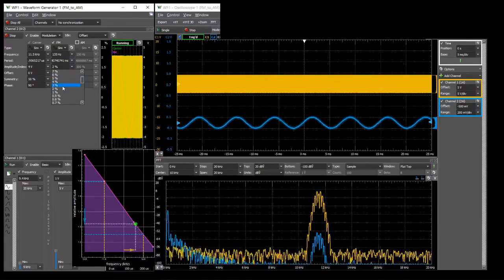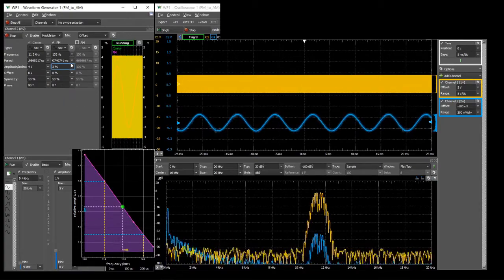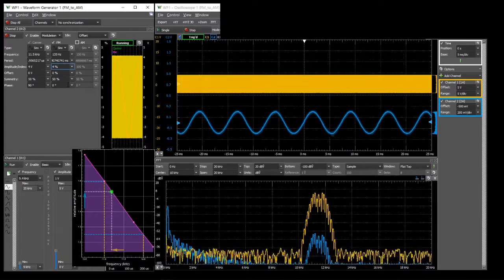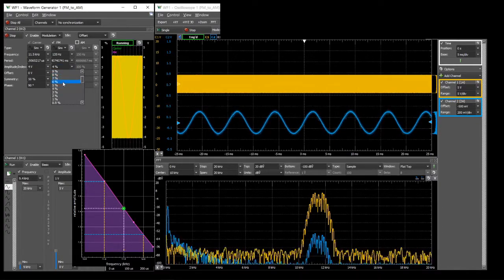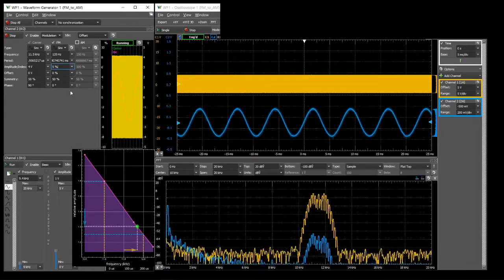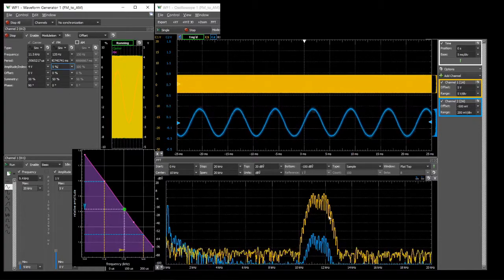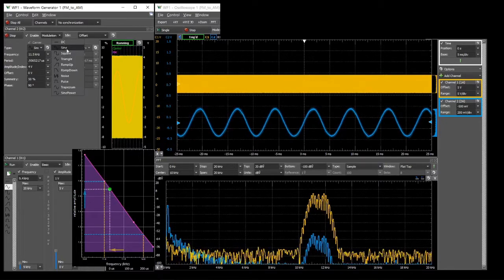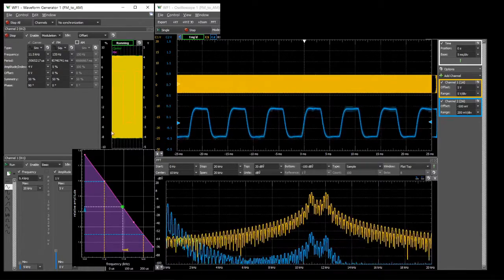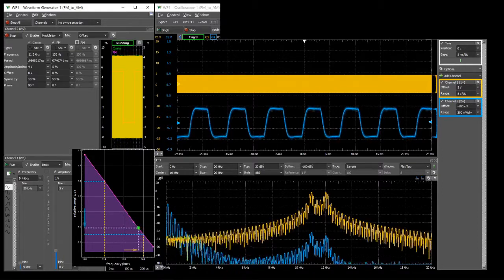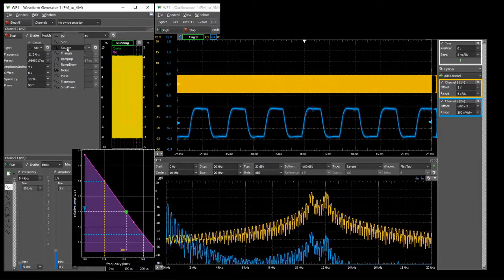The Fourier spectral line is broadened, or its bandwidth increases, as it includes the modulation rate. A more important factor on the bandwidth is the modulation amplitude. It widens as the modulation amplitude is increased. Waveform, or modulation format, also affects the bandwidth as shown. Frequency shift keying, or square wave, costs the highest bandwidth as evidenced, which is true for any modulation with discontinuous sharp edges.